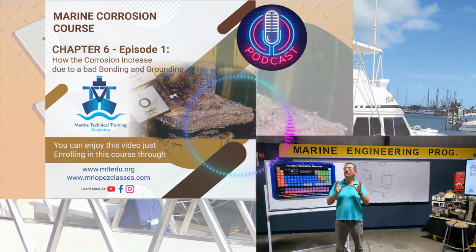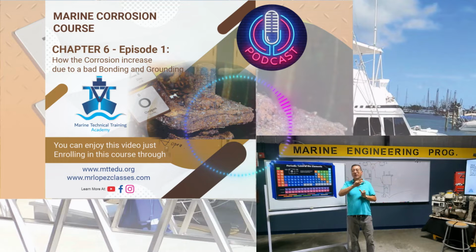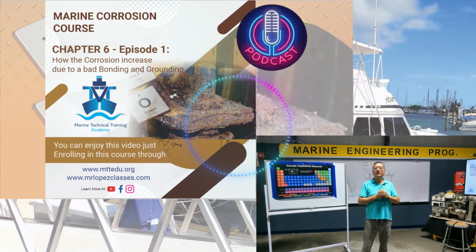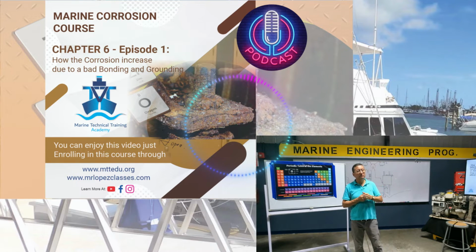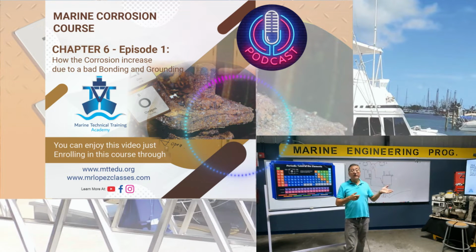This is no ground. The batteries on the flybridge are not connected with the batteries in the engine room. Those battery banks are not connected at the negatives. In other words, the negative is critical. The ground is critical. But let me refresh a couple of concepts before I continue with the explanation related with the ground.